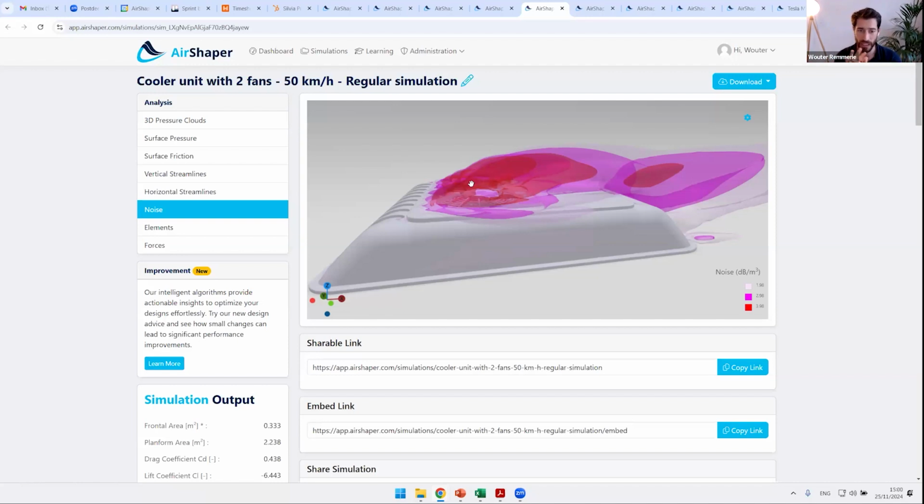So keep in mind, if you want to run a fully detailed acoustic simulation, you do need an extremely precise mesh, and you'll probably have to go to a transient simulation. Nevertheless, for large car OEMs and so on, we've been able to really reduce the noise, or at least provide them with lots of insights as to where the noise is coming from using this technique.